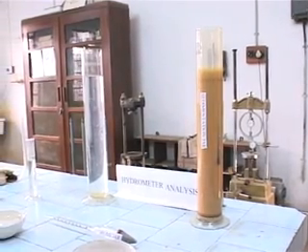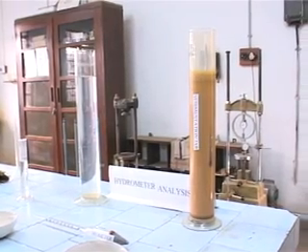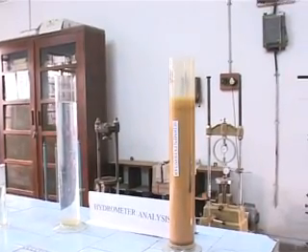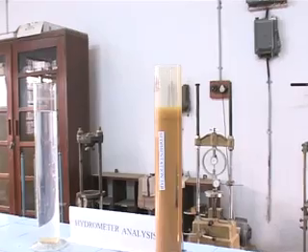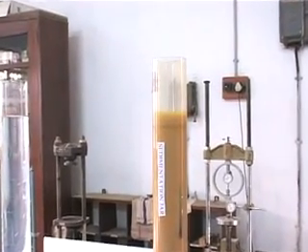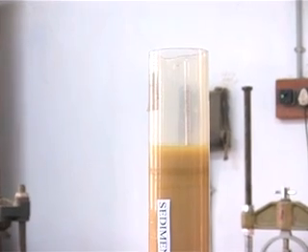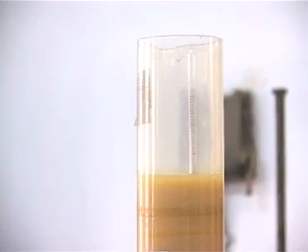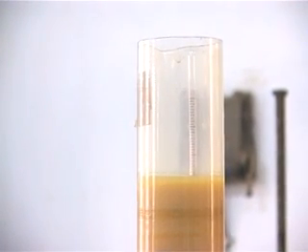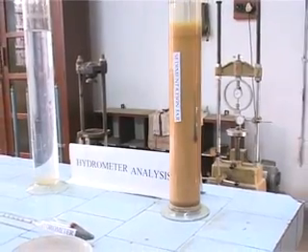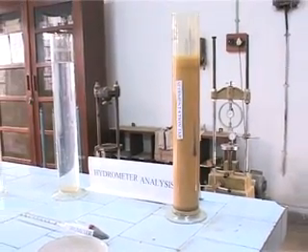You should also note that the reading has to be corrected for the temperature at the date and time of testing, because that is going to affect the specific gravity or the viscosity of the slurry, which is required in application of Stokes solution to this particular problem.